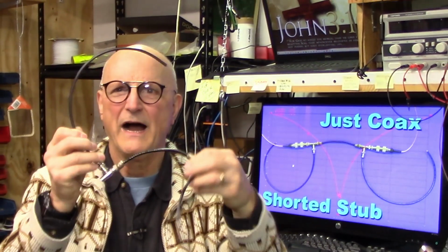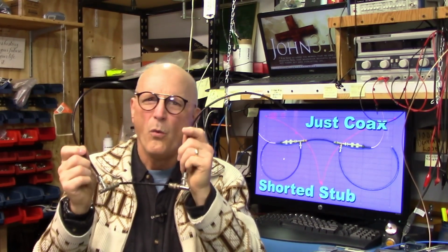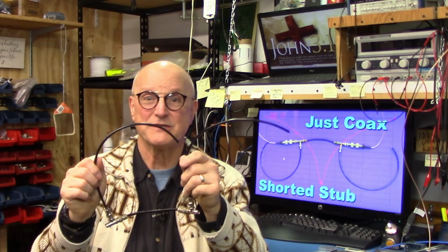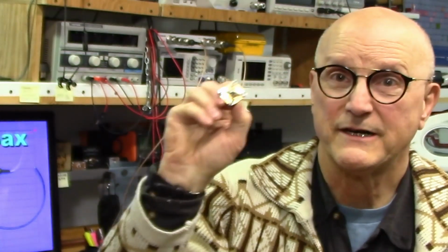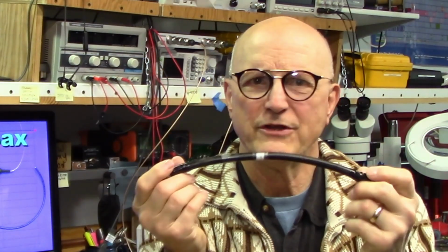But you know, one problem with shorted stubs is the length of the stubs. A half a wavelength can get pretty doggone long at lower frequencies. Wouldn't it be nice if we could do a better job of tuning and shorten the length of the stubs at the same time? And the answer to that question is, we can. But how? Suppose we were to replace our dead short at the end of the coax with some kind of inductor. Well, this fools the system into thinking that the coaxial cable is longer than it really is. The shorter the coax is, the larger the inductor you need to make it appear to be the length you need. But there is a limit to this.